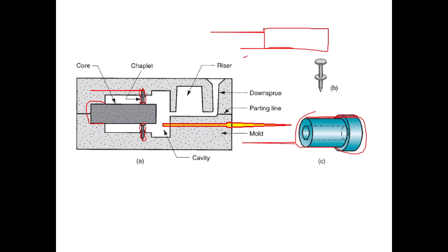That force system can be replaced with a resultant force. Say that F sub m is the resultant of the force system. It is applied by the mold onto this end of the core. And the turning effect of the force system can be represented by this resultant moment. It is the moment of the forces applied by the mold onto the core. It is at this end.